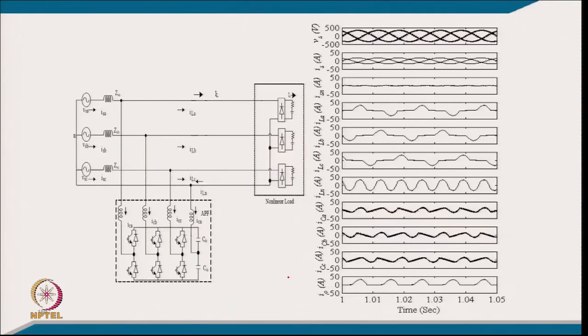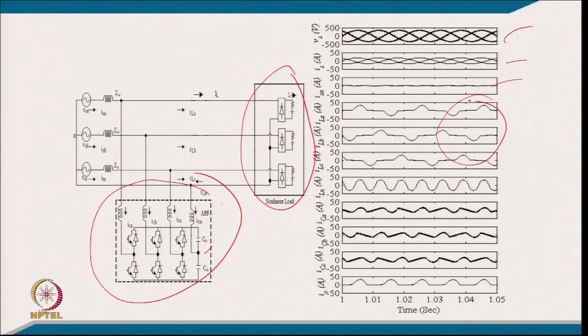So, this is the system that we have, a battery charging load for all 3 phases equal with the 2 ohm resistance in series, and this is the 4-wire shunt active filter, with 3 legs, but the neutral is connected with the midpoint of the capacitor. So, after designing and simulation, these are the 3-phase voltage, 3-phase current, and the neutral current of the supply is made 0, and these are the 3-phase load current and neutral current of the load, and the 3-phase shunt active filter current, which typically carries the load current harmonics.